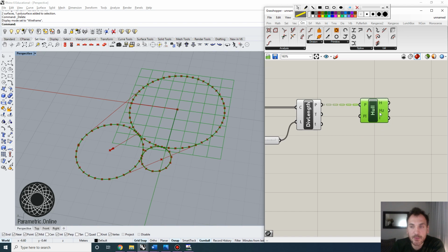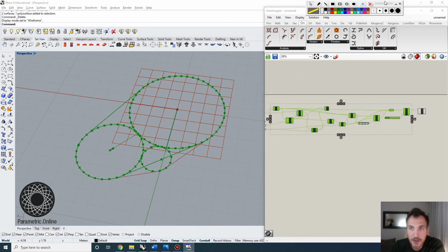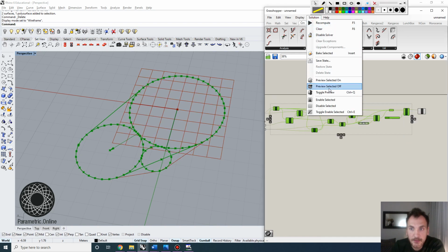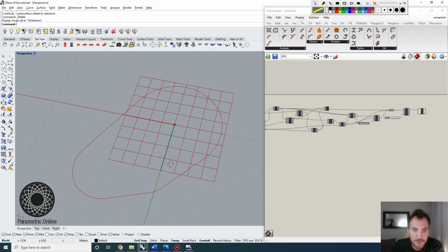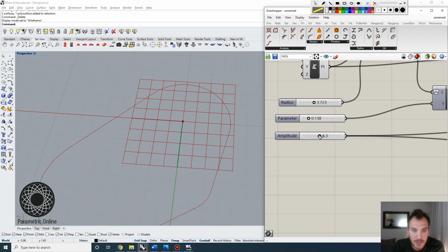But we don't want that. We actually want the cumulative computation of the convex hull. So you need to right click here and flatten this list so it becomes a singular list. And now you can see we have actually acquired a polygon shape that contains this initial construction. If I go here and hide my construction, you can see that this is the polyline that contains the shapes that we had.